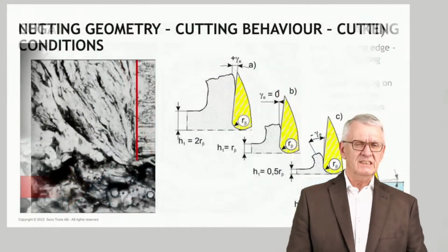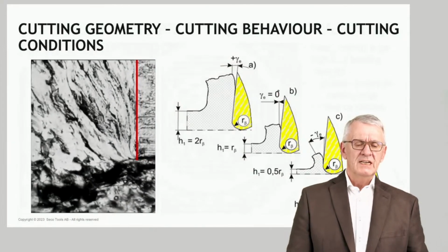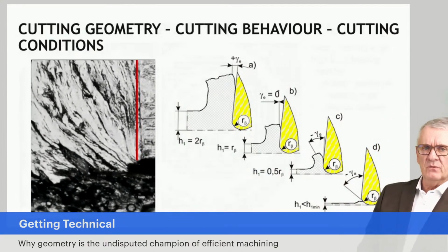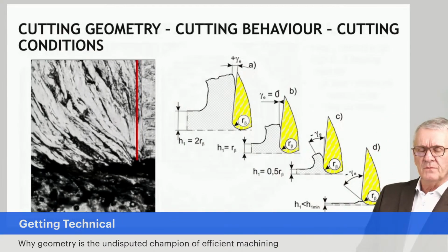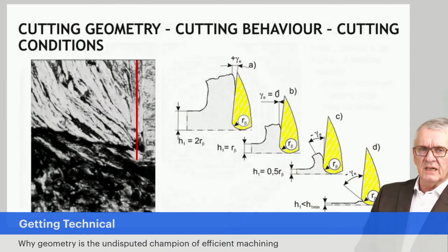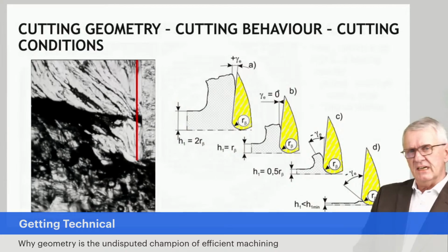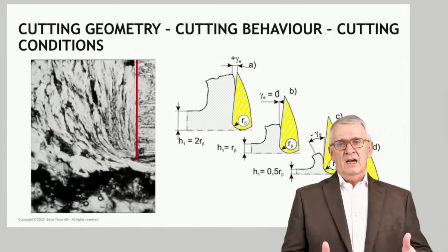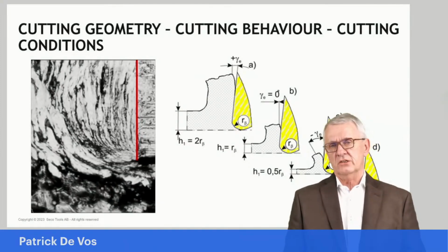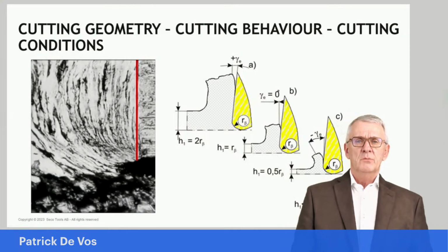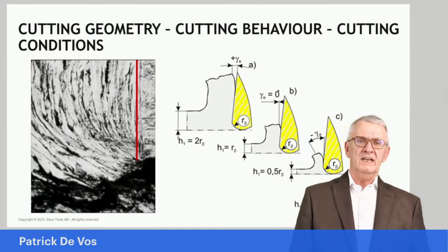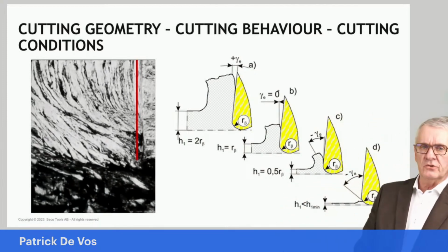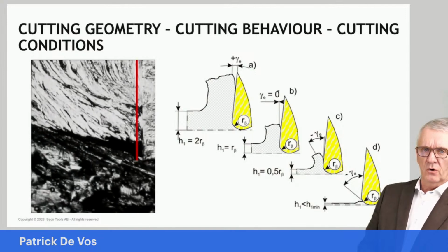That's in the end what we do with geometries. Now we have to be careful with geometries, and I try to illustrate that with here 4 pictures. I think the video itself is perhaps not so clear, but anyway. You see here 4 times the same cutting tool with the same geometry, rake face geometry, cutting edge geometry, cutting edge line, everything is the same, but I use the tool with, from left to right, a big feed, a smaller feed, and the one to the right is a very small feed.